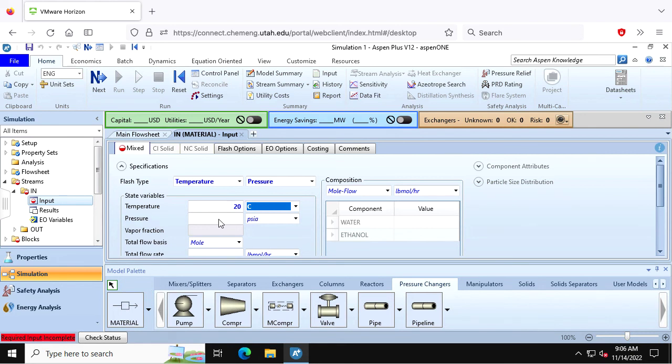But the reason they use it at all is that back when chemical plants were being built 100 plus years ago, they didn't have all the cool electronics like we do to measure things. So if they wanted to measure the pressure drop across an orifice plate, they would use either a manometer or what do you call it when it's dual-sided? But you understand what I mean. To measure the pressure difference. And you would actually look at it.